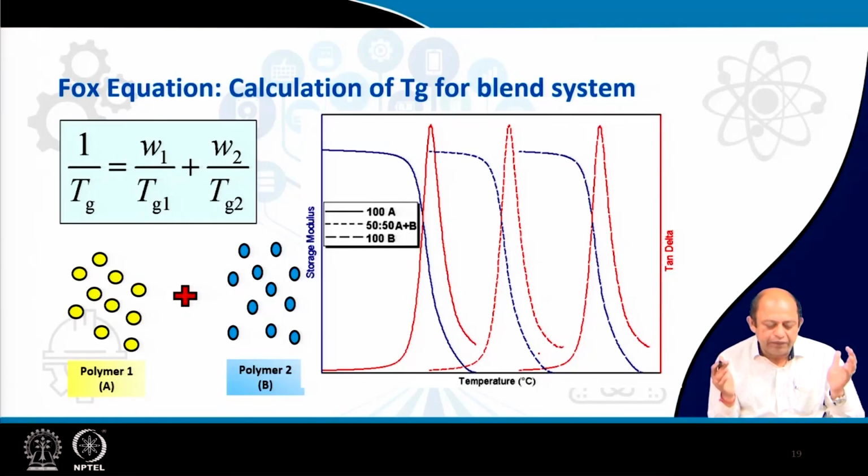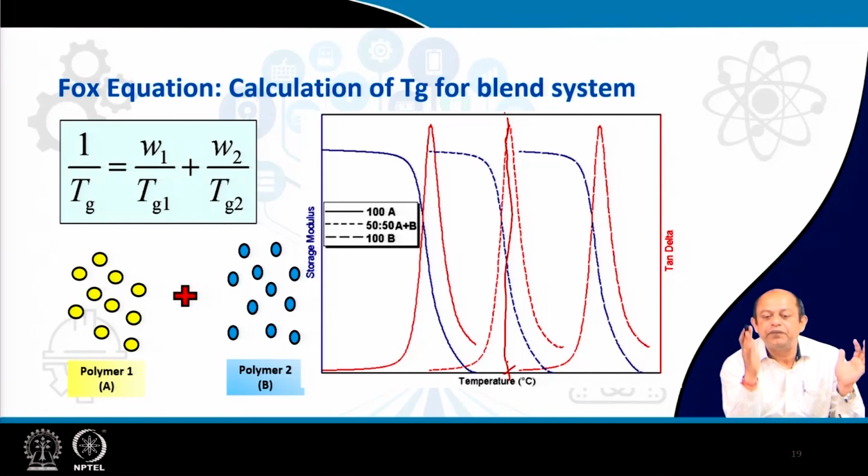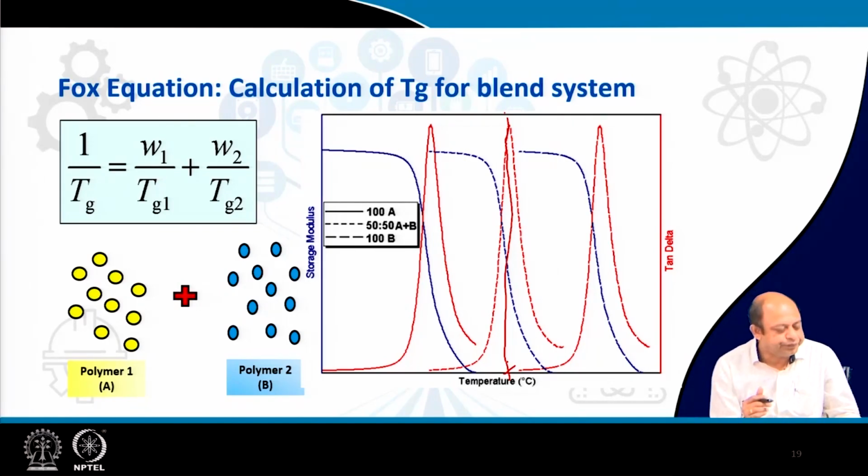See, this is what exemplifies: polymer A, polymer B, we mix them. Had it been a purely miscible blend, we would get, based on the Fox equation, a Tg somewhere in between, at the midpoint; otherwise we get two Tgs. You can monitor either, as I mentioned, it is up to your perspective, storage modulus or loss modulus or tan delta, and we will try to see that shift.